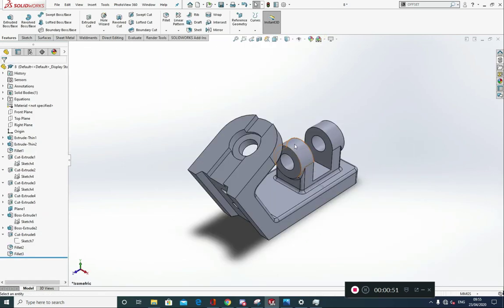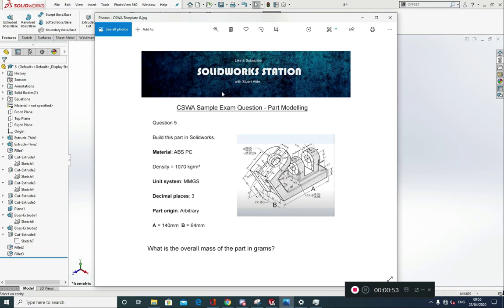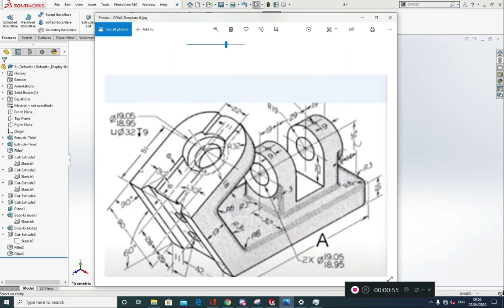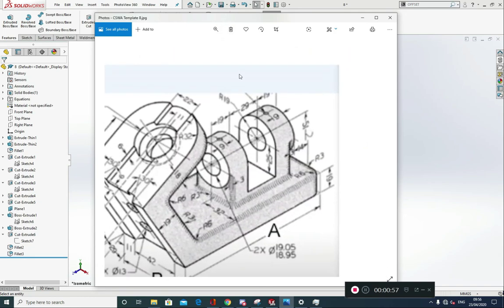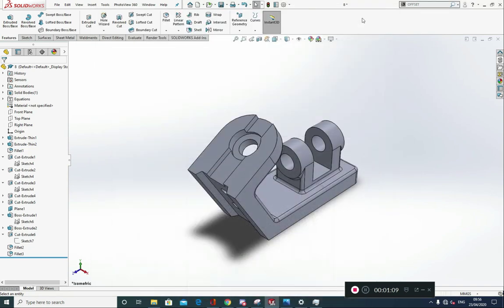So we need to put some holes in the top of here. So if I just go into my engineering drawing, I'll just show you. I have clipped the dimension off here, okay, but these circles are diameter 5. Okay, so it sits 9mm from the back face, 9mm from the front face. There's 2 of them, and they sit central on that particular shape at diameter 5.